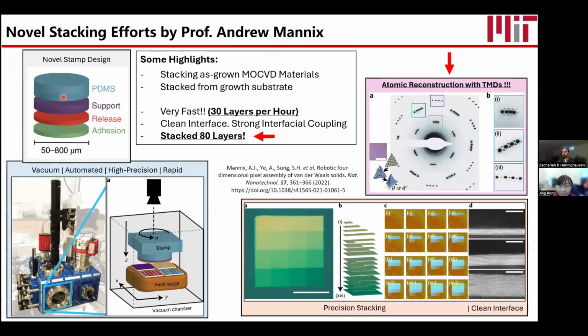Smart idea. I think it also allows better spin coating. He also has a release layer where the polymer breaks down when heated. And then there's the adhesion layer, which is the really important one. It uses a polymer called PBZMA. Feel free to email, I can give you the exact details, but it's known for being a sticky polymer, and there are some arguments for why it's a good one to pick. But I'm following Professor Mannix's research in this case. PBZMA is a good choice, and it spin coats.